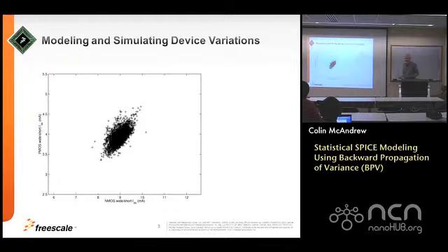So what do you need to do in statistical modeling? What I'm showing here is from a half micron technology, and I'll use this data set for some of the examples here for two reasons. One of them is because I have tens of thousands of data points from this technology, and secondly, because it's a half micron, it's not affected by local variations, which is mismatch, the microscopic fluctuations. It better highlights the way that the global characterization gets done.